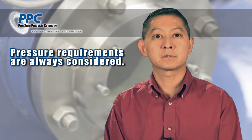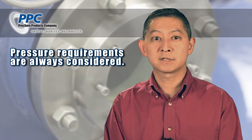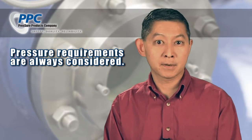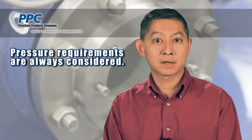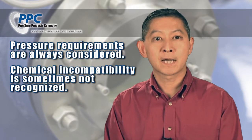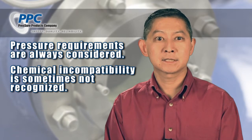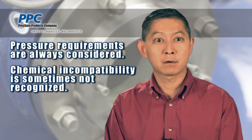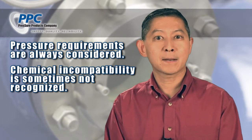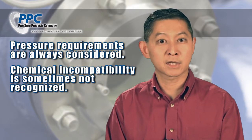Chemical corrosion failures are much more common than pressure-driven blowouts. In fact, I'll go so far as to say that chemical corrosion has ruined more sight glasses than all other failure modes combined. And the reason is that, unlike pressure, most people don't think about it before specifying a side window. What exacerbates the issue is that window materials, plastic and glass, are both commonly considered to be corrosion resistant. But nothing is resistant to everything, so for any given application, it's very important to make sure that window is not reactive towards the process fluid.